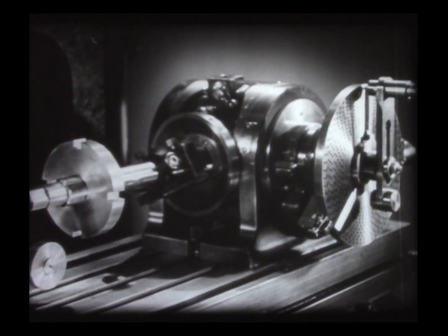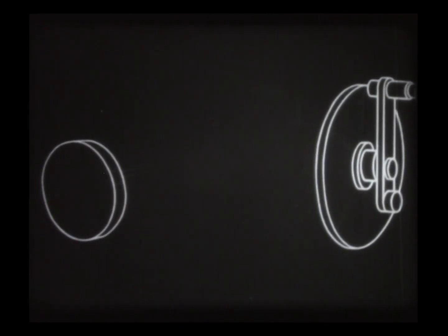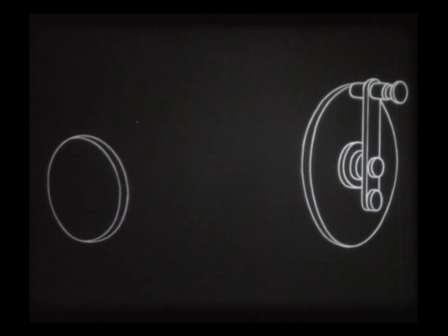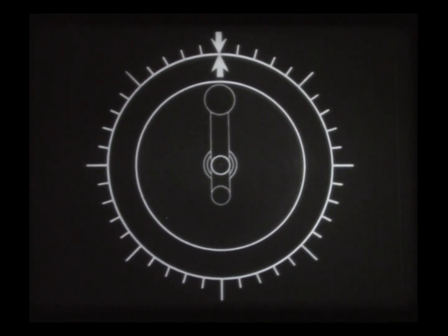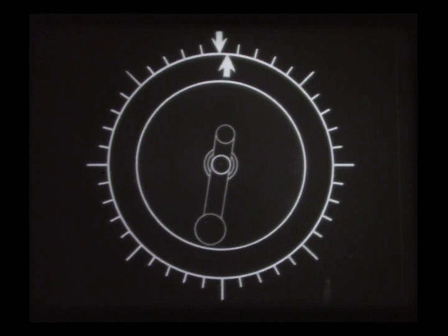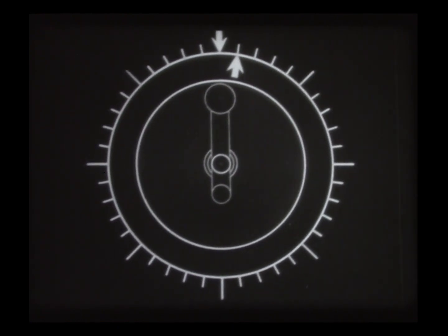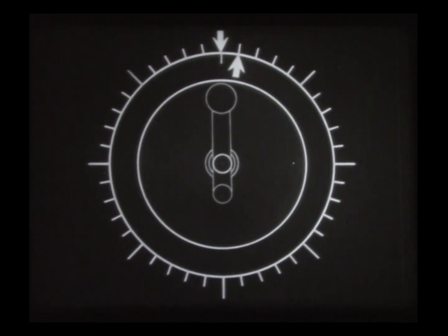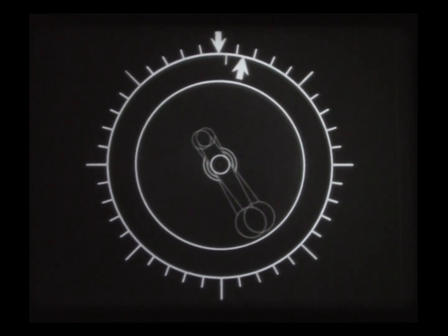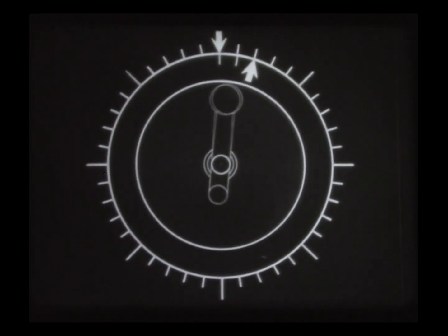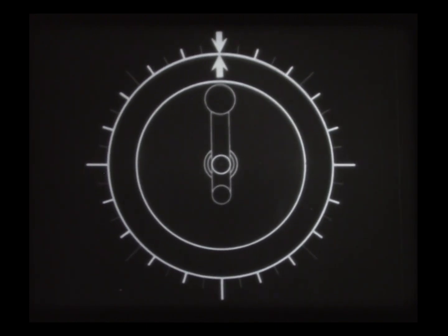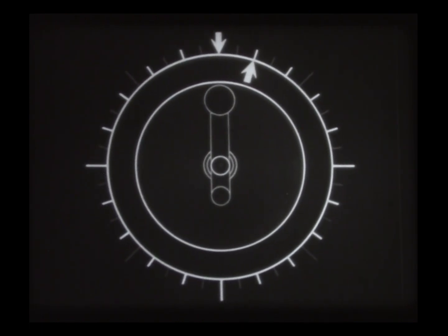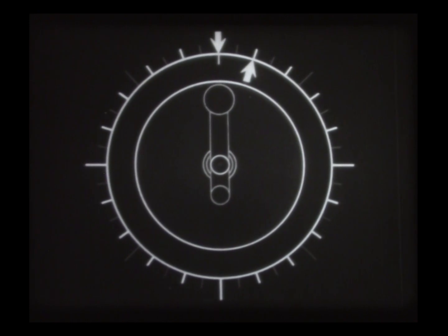The operating principles of the dividing head can be further simplified by imagining the hand crank to be centered directly in front of the work. If 40 equally spaced cuts were wanted, each full turn of the crank would move the work 1/40th of a complete revolution, thus locating each of the 40 cuts. If 20 cuts were wanted, 2 full turns of the crank would move the work 2/40ths or 1/20th of a complete revolution, locating each of the 20 cuts.